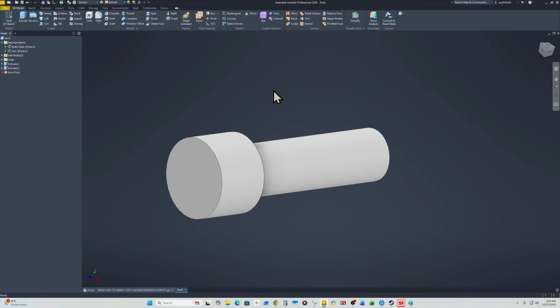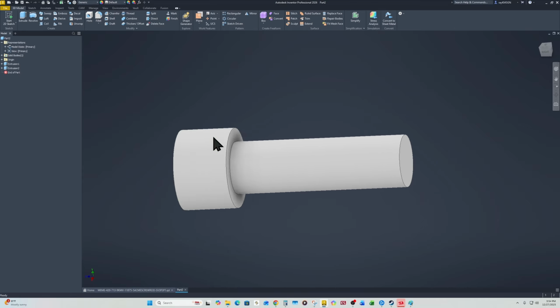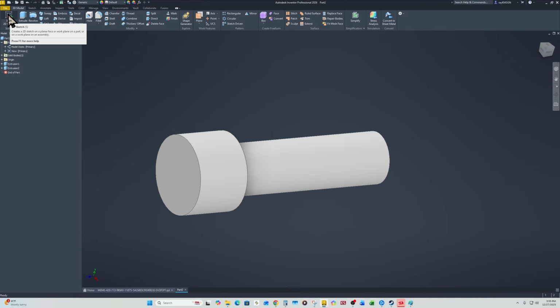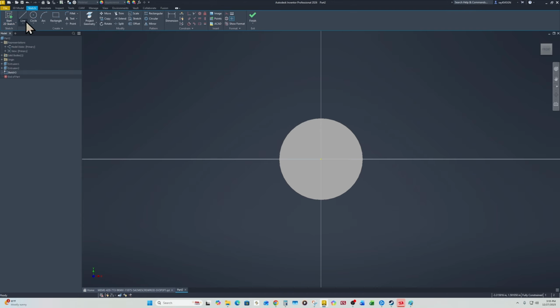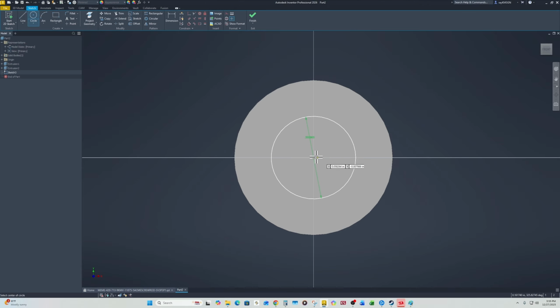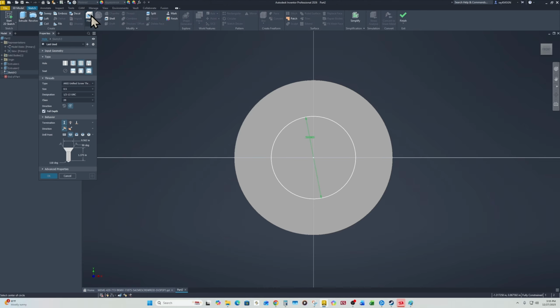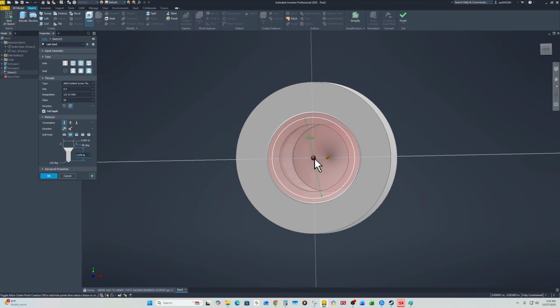And let's do the hole real quick. I believe that's gonna be 1/2 inch diameter for the hex. So we're gonna start 2D sketch. We're gonna start on this face. And we're gonna do tab 0, tab 0, tab enter, and that's gonna be 0.5, enter. And we're gonna do 3D model, and then we're gonna do hole actually, so we can get the angle at the bottom. We're gonna select this, we're gonna move the view.